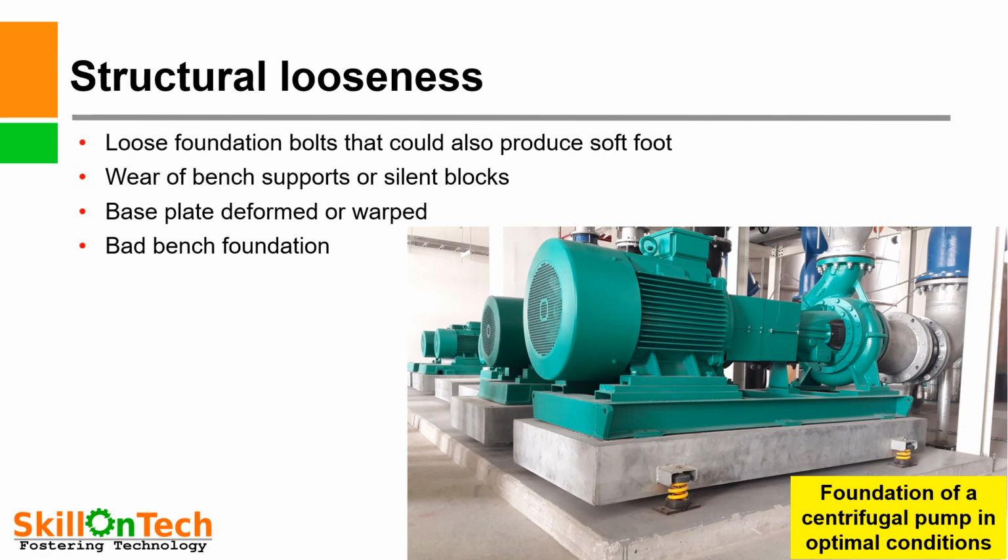Here you can see a picture of the foundation of a centrifugal pump in optimal condition. You can see this foundation is made appropriately. Here is a concrete foundation, then this is another concrete slab where these are the anchor bolts in concrete, and this is the structural foundation base of channels, and here this pump is bolted to the structural channels. Similarly, this motor is also bolted to the foundation.